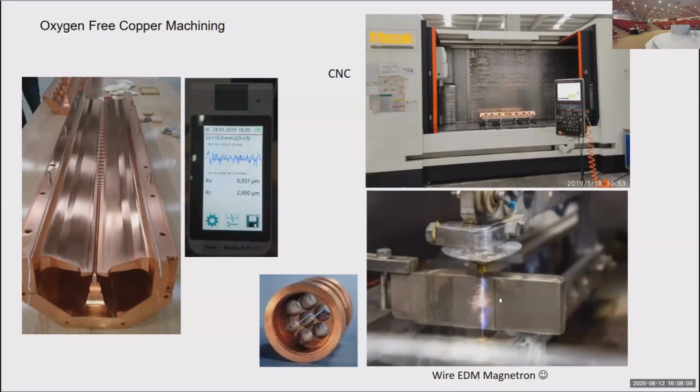The wire in industry, in normal cutting, is about 100 to 200, or mostly 150 microns. But I have seen 5-micron wires in thickness.